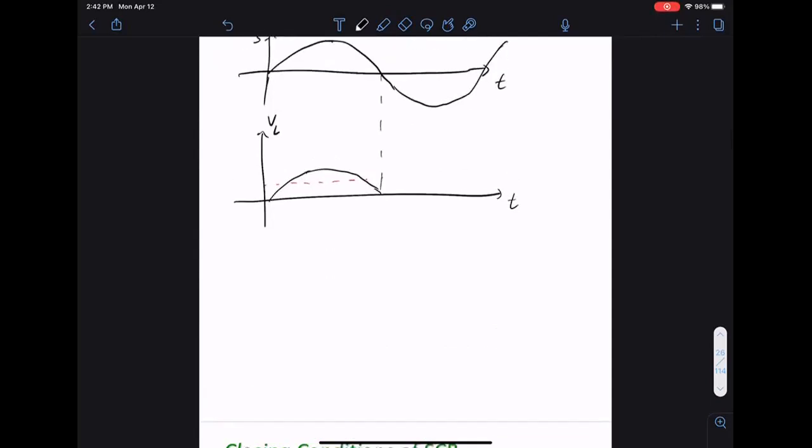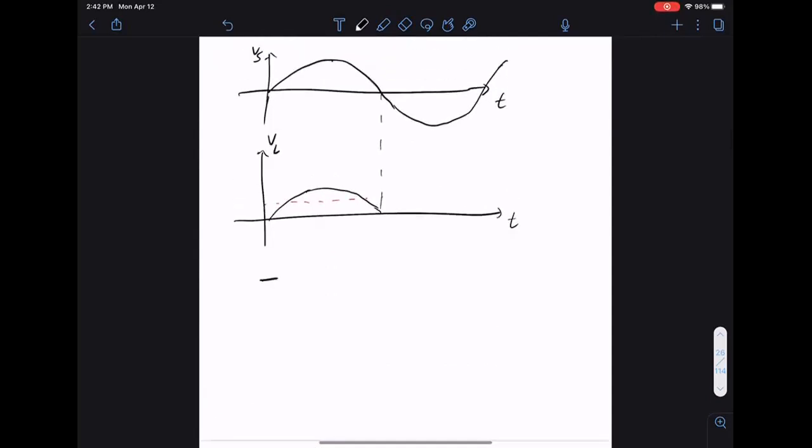So one simple way to do this is actually to add a switch. So let's add in a switch. With a switch, we can time the switch to give us only part of the waveform. Let's make sure it's DC, so I'm going to add a switch with a diode. And then I'm going to time my switch as off, on, this kind of thing.